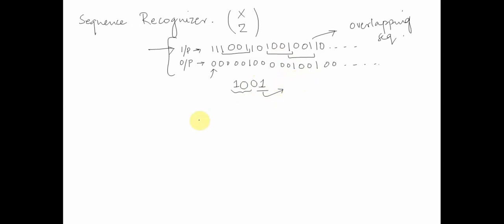So now in order to make a state table or a state diagram, we can start with a state diagram, right? So if you have to build this sequence recognizer, let's assume that we have, how many states would we need, right? We need to identify 1 0 0 1, 1 0 1 0 0 and 1 0 0 1. So let's assume that we have four states, where we designate state A as none of the pattern is observed. State B is something like we have seen